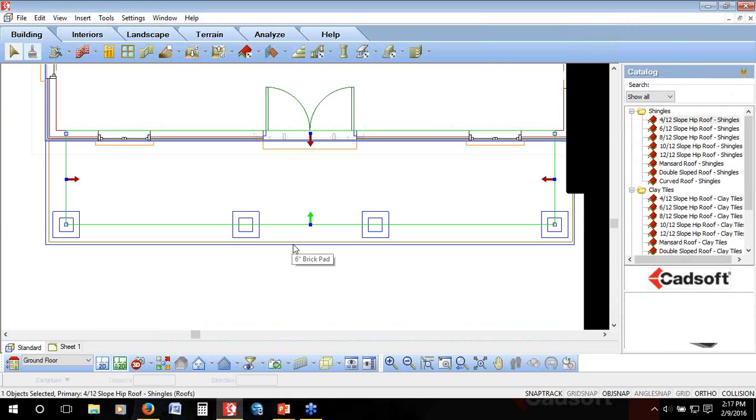But what if our client wanted a little bit more detail by the front entrance? So instead of just being a shed, they wanted to break this portion out at the front to form a little gable end there. How do I do that? Because if I change this into a gable, that means all 4 sides will be gable and they'll all just pitch right up. I need this to remain a hip so it knows the plate height and it knows the pitch. So I want it to be hip, gable, hip. And right now we only have 1 arrow, so how can it hold 3 different styles?